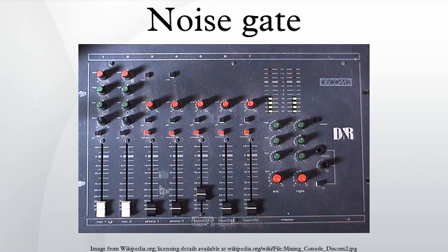Sound reinforcement. Noise gates play an important role in drumming and heavy metal shows. The drum and cymbal mic channels will typically have noise gates so that the mic will only be turned on when a specific drum or cymbal is being played. This dramatically reduces bleeding between the drum mics.